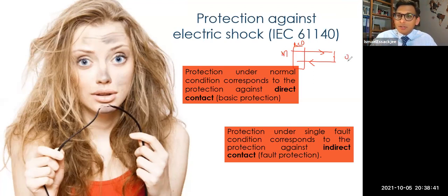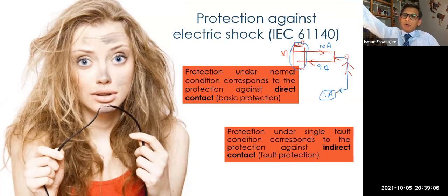But let's say you are here and you are touching it, and it is giving you an electric shock. So current is supposed to be flowing through you and going towards the transformer, whatever. This is going to create an imbalance. It may be 10 ampere here, 9 ampere remaining, and 1 ampere going through Earth. So this imbalance is going to be seen by the RCD, and it won't wait for it to be 1 ampere, because at 1 ampere you are already buried.